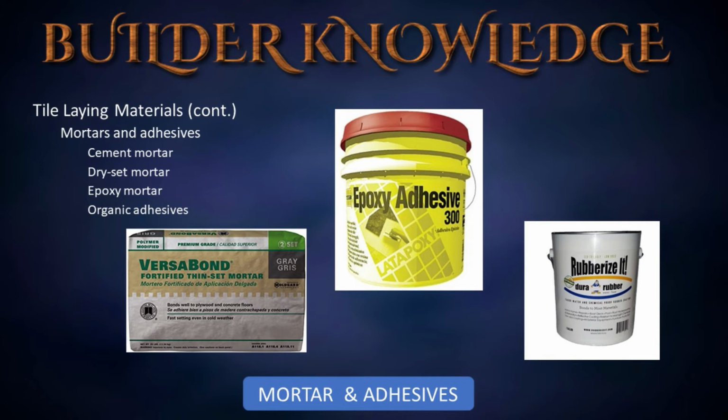Organic adhesives, or mastics, are solvent-based, rubber materials. Porous materials should be primed before any mastic is applied. Suitable surfaces include wood, concrete, masonry, gypsum wallboard, and plaster. The bond strength varies considerably among manufacturers, but the average is about 100 pounds per square inch.